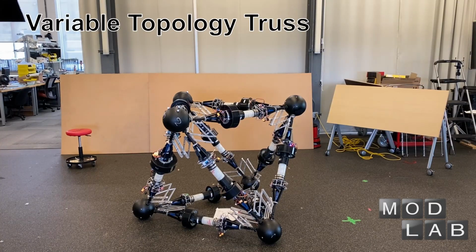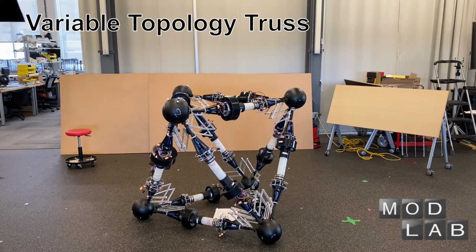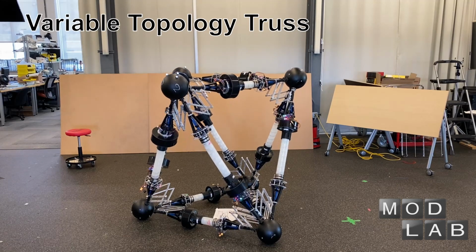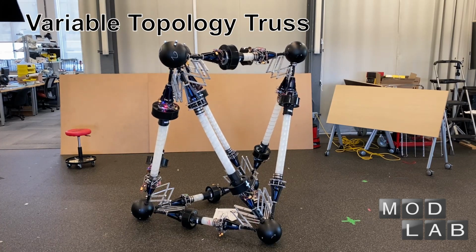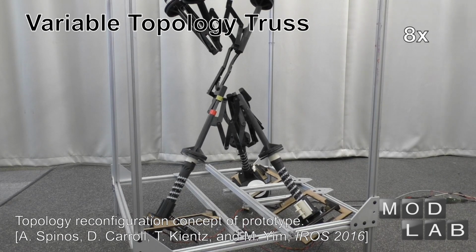A variable topology truss, or VTT, is a modular robot in truss structure. Each module contains a spiral zipper prismatic actuator and a mechanism for attaching the ends at truss nodes. The node enables linkages to remain connected during the motion, and the geometry shape of a truss can be changed by moving nodes around. Furthermore, two nodes can be linked in an open chain to do topological reconfiguration.